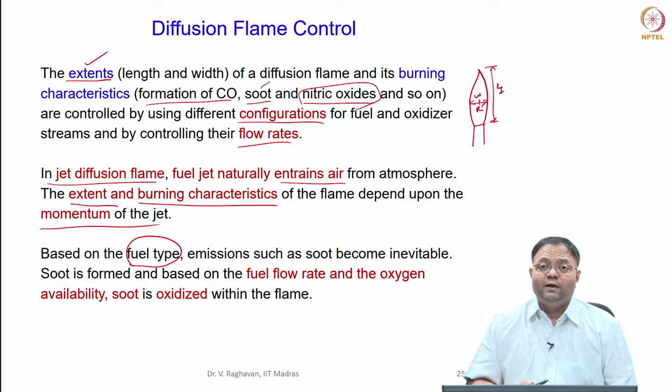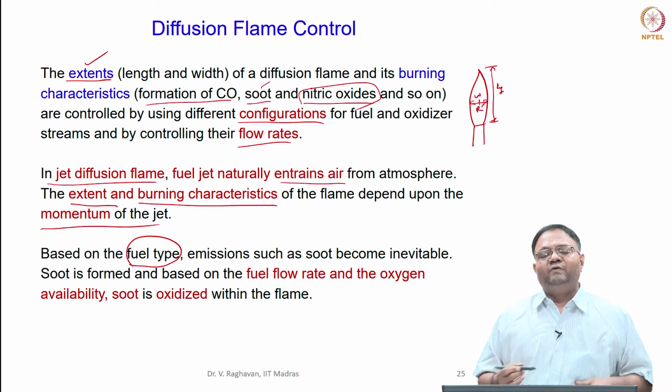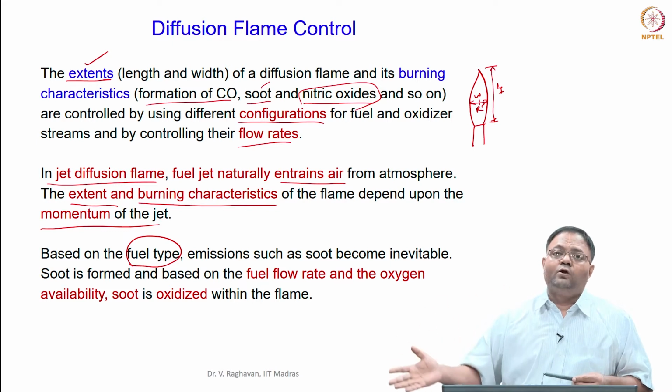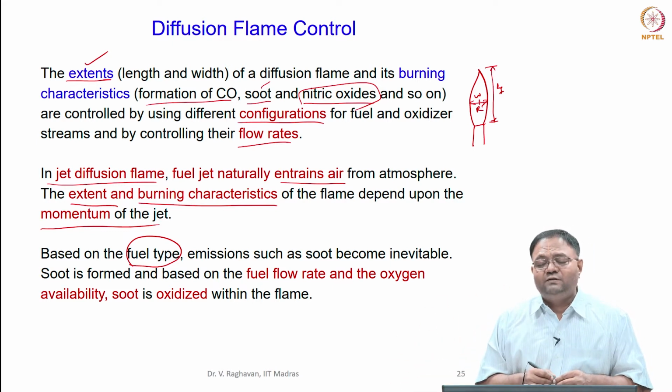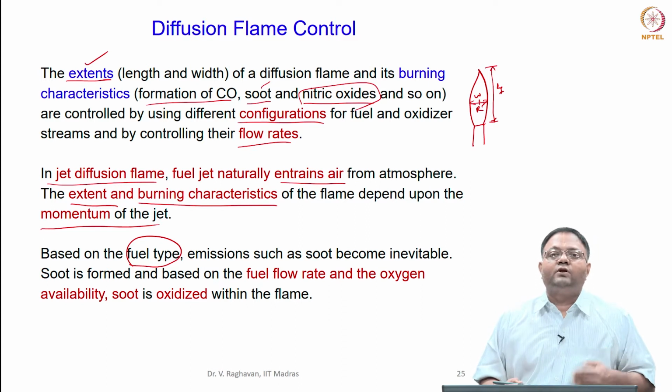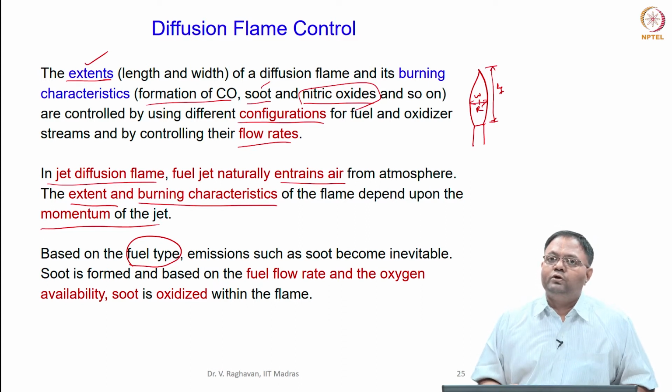The H/C ratio is 4 and it burns nicely. However, when you go for higher order hydrocarbons, say heptane, the fuel has to pyrolyze to smaller hydrocarbons, and when it does, we will also end up with unsaturated hydrocarbons like C2H2, C2H4, etc.